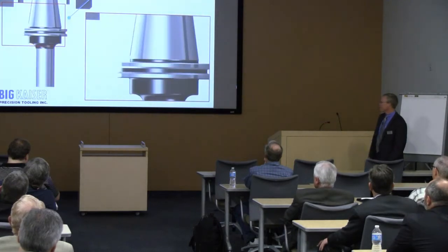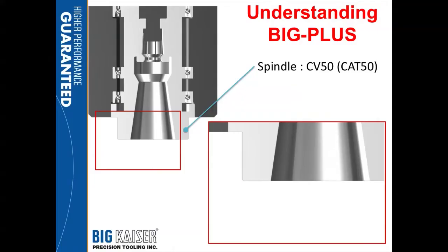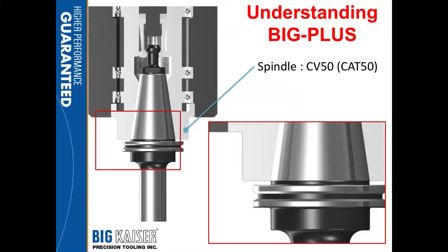Because when I put a tool into it, I always expect a gap. In most CAT 50 tools, you see about an 1/8 of an inch. So that precision is just not needed. There's nothing contact. It's an open tolerance.